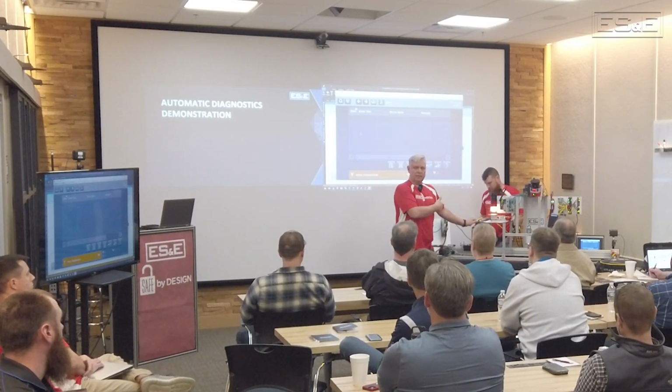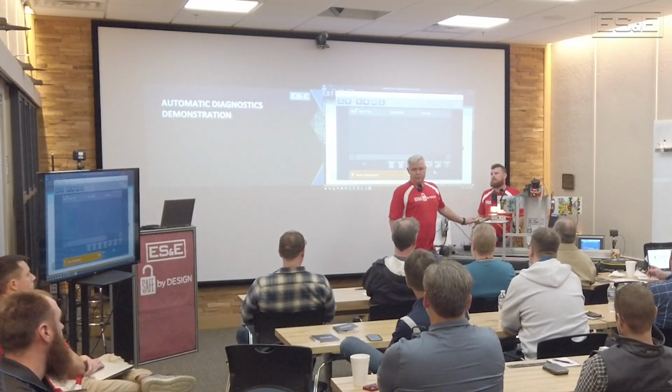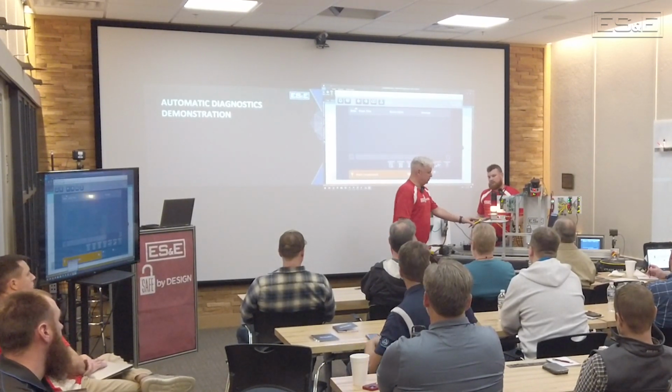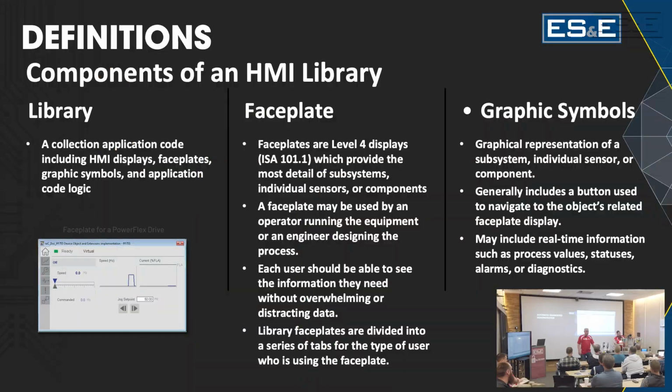Especially with this new block. It's not going to do this with the older 1732 block, but it will do it with the new one, because those devices are actually listed in the I/O tree of the processor, what it's connected to. So that's kind of a cool feature too. You get that for Ethernet, you get that for I/O link devices.